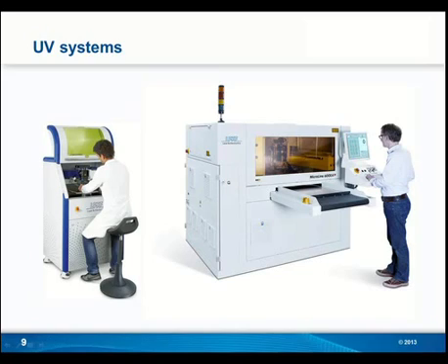Kelly, I think I've actually spoken to you before, so I think you should just give me a call or send me an email. I'm not sure that I understand your question fully with the microjoints. I think you're maybe talking about tabs, but with depaneling in general, you're able to either depanel the full part, depanel only a tab, or depanel most of your circuit and leave a tab. So you have several options. Whatever you design in your data is what the laser is going to do. But yeah, please give me a call or send me an email and we can go more deeply into that specific application.